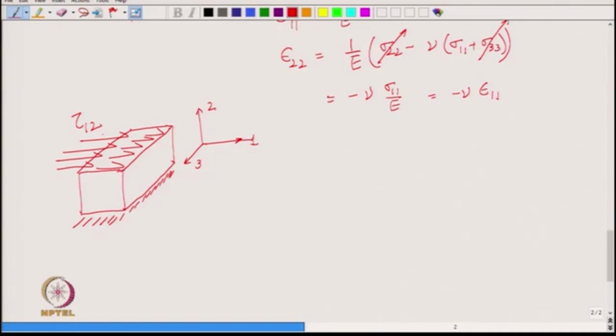and then what do you think is going to happen as you apply that shear force? The bar is going to shear. Is not it, the bar is simply going to shear, and then what would be the shear strain? That is this angle, the change in angle between two perpendicular line elements, remember. So, initially the red lines which are perpendicular, they get inclined, and that is the change in angle, which is also gamma 1 2, is not it.